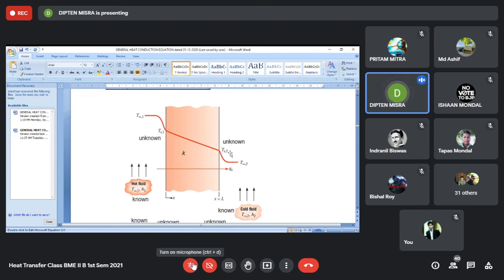And what we have seen is that if we make the wall thicker, then it will have a larger resistance. If we use a material that has a low value of conductivity, it will increase the resistance. Then the heat transfer rate will be reduced. But there are disadvantages to this. If you want to increase the thickness of the wall, then the carpet area of the room becomes less. So I can make the thickness of the wall maybe twice than what is being done presently.